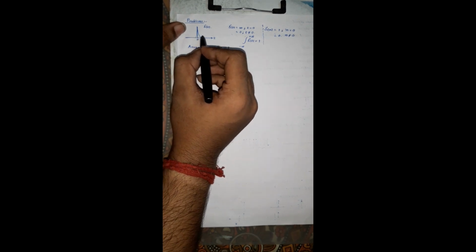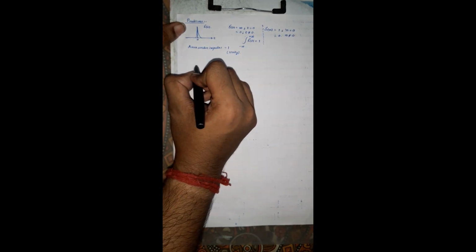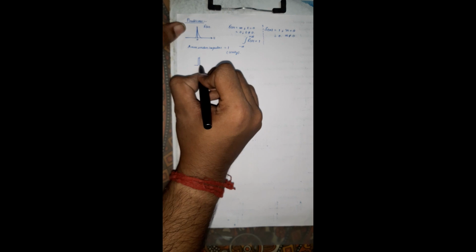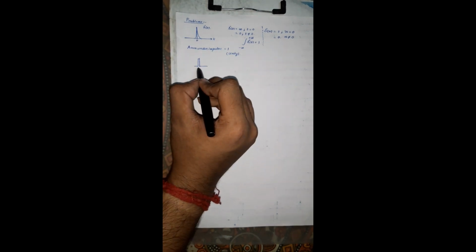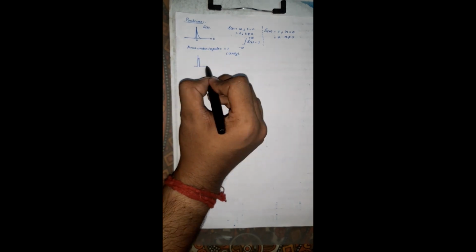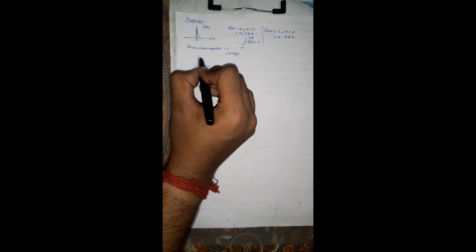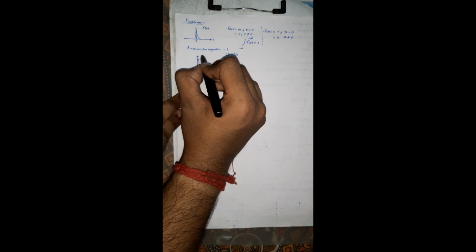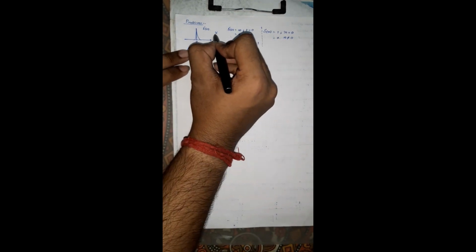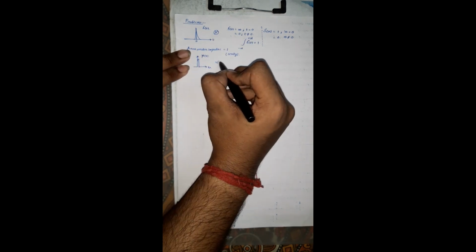We can't generate impulses in the time domain, but we can generate a square wave or a pulse of very small width. This is possible, right? Because this pulse has some finite duration as well as some finite values. Though the duration is very small, there is a finite duration and it has finite values. So this pulse can be generated. This cannot be generated, but this is possible.